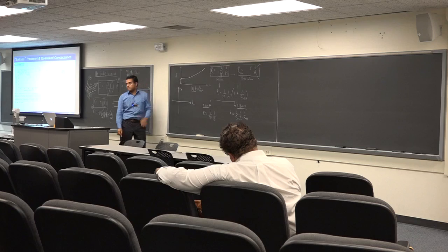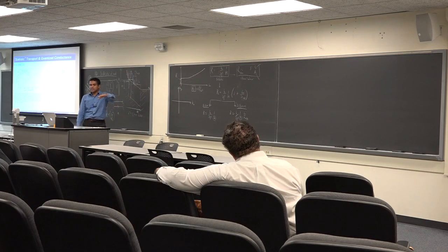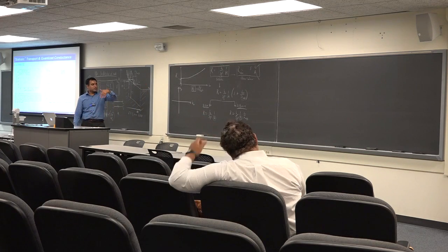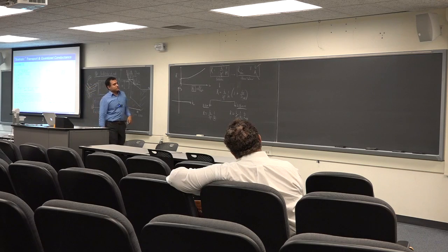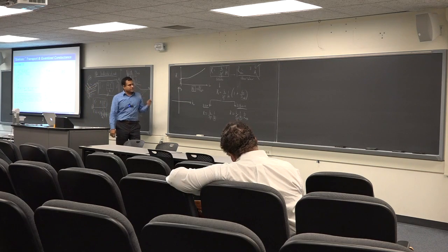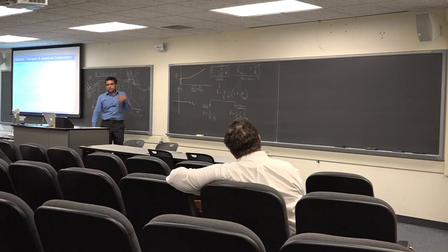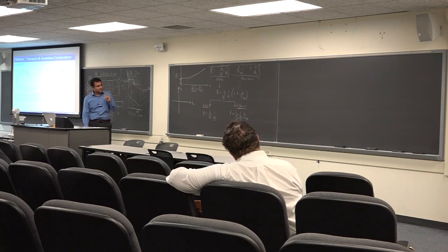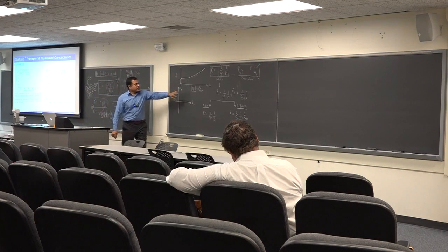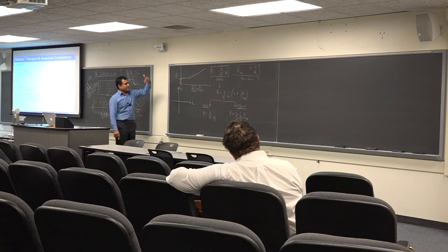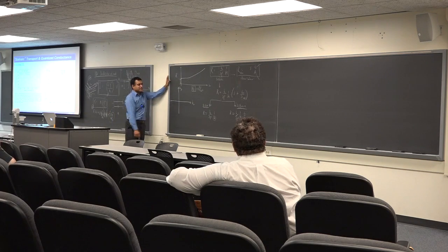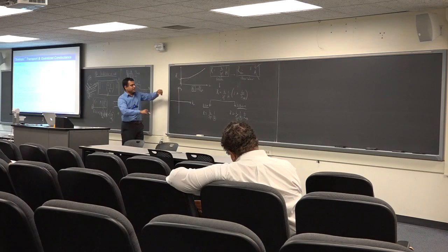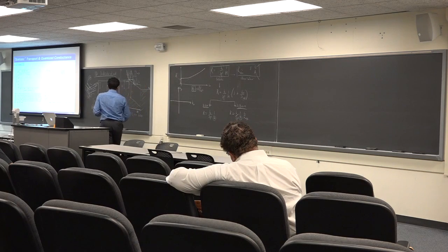That's the sheet density of electron, the two-dimensional electron gas density that we create using a gate, or sometimes using some other techniques, polarization, modulation doping, something like that. We create this electron gas. Okay? So in the process of creating this electron gas, how have I filled the k space, right? I mean, remember in k space, if I have a 2D electron gas in a plane,